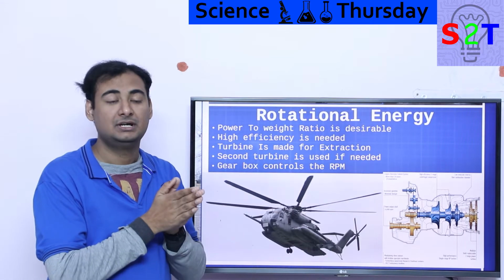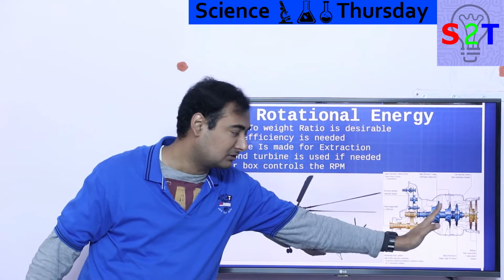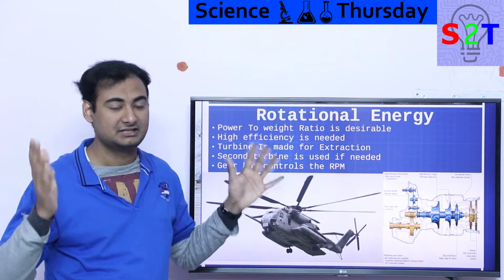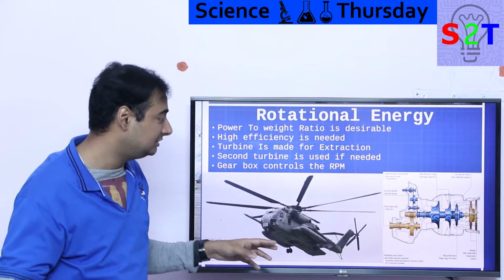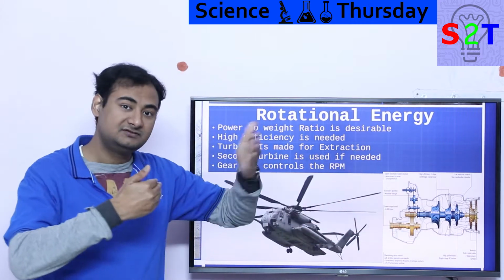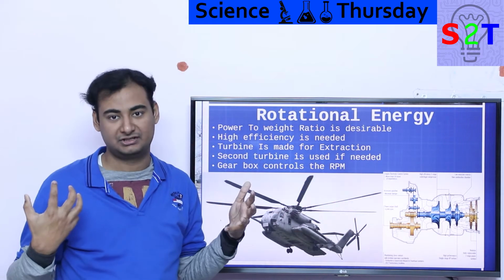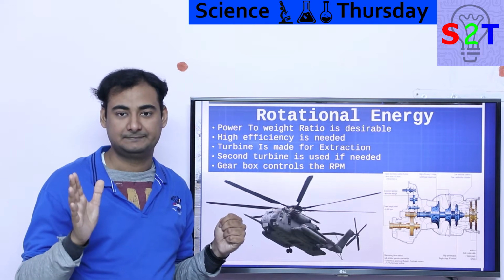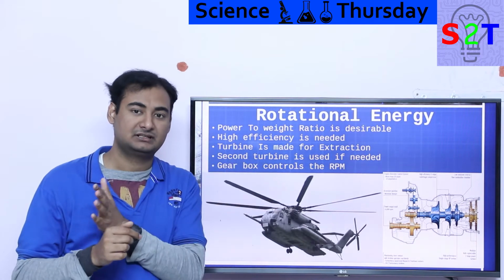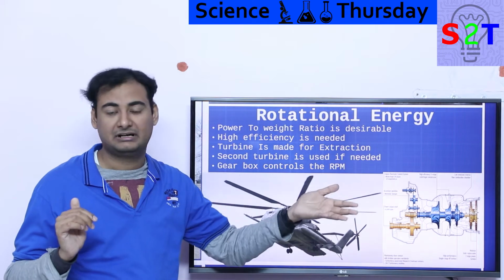So sometimes you may have a normal turbine system that we're not going to touch, because it's, let's say, taken from a jet engine, a jet plane. You don't want to tamper with it. All you will do is put a second turbine in that exhaust, and that will extract most of the energy out of it. So let's say you got 10 megawatts from your chemical energy, 2 megawatts were taken for running the compressor, then you have 8 megawatts.